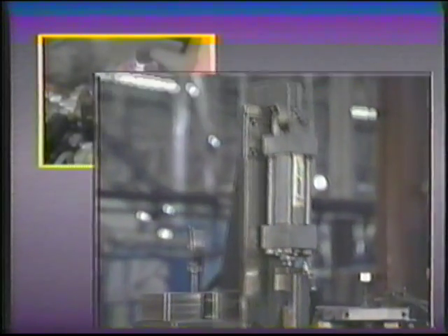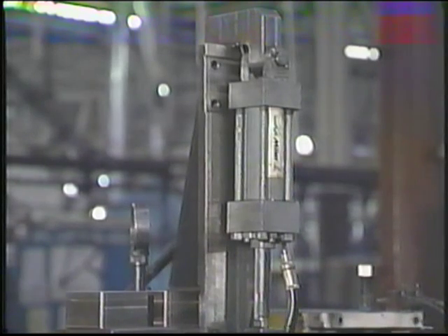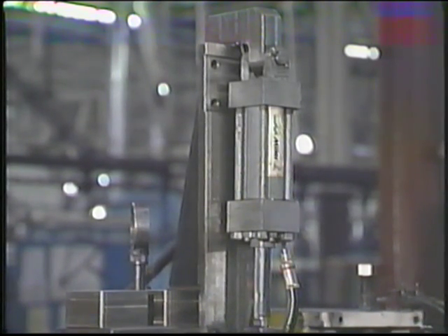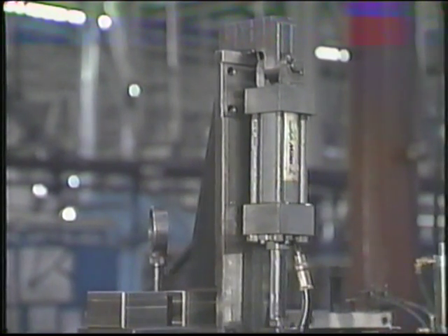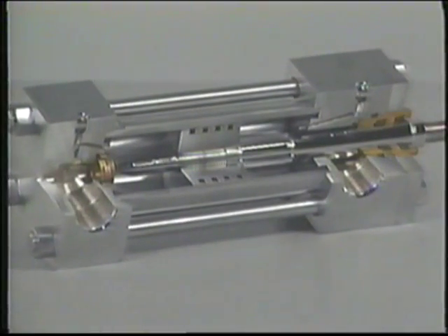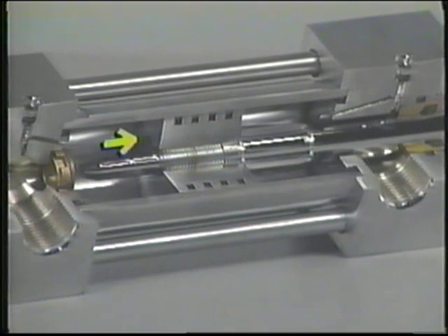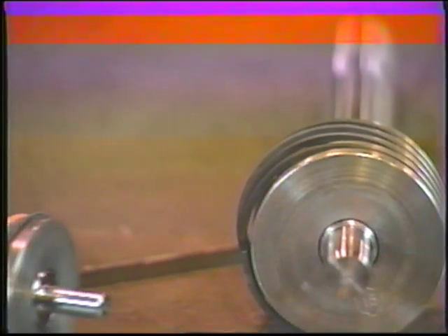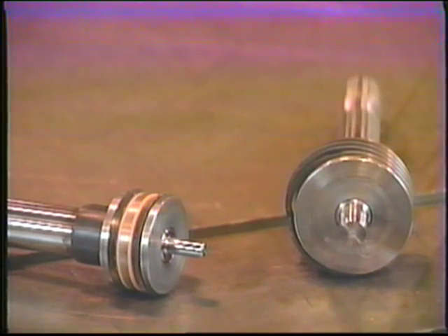Okay, now let's take a look at hydraulic cylinders. You'll remember from earlier lessons that cylinders are used to convert the energy of pressurized fluid into mechanical energy. In a cylinder, the pressure differential between the cap end and the rod or head end of the cylinder can be very high, so the piston must be sealed at the cylinder body to prevent leakage as the piston moves the rod in and out. This is done with cast iron piston rings or with seals made of a flexible material.